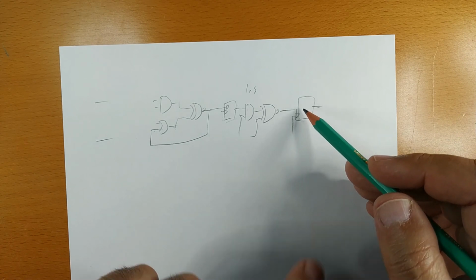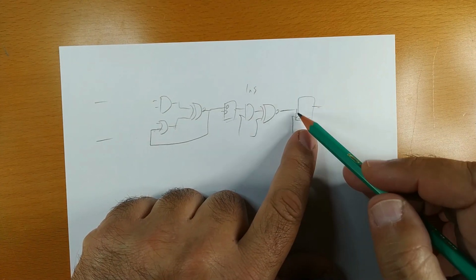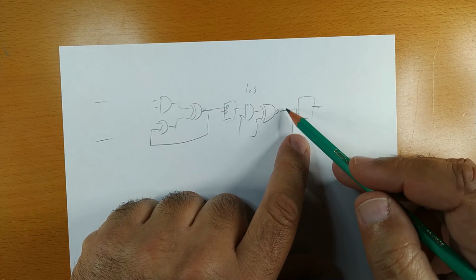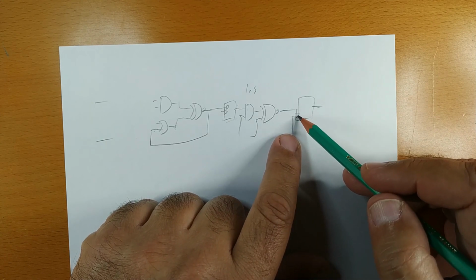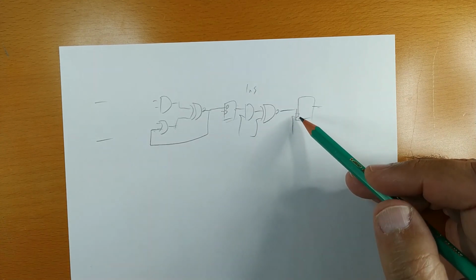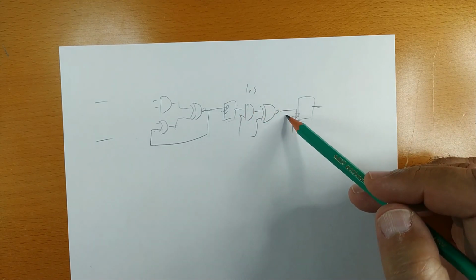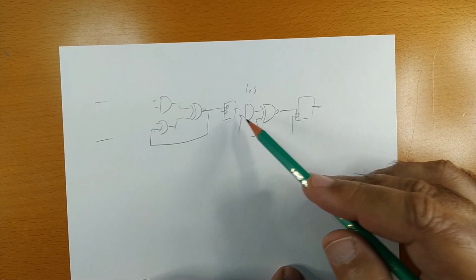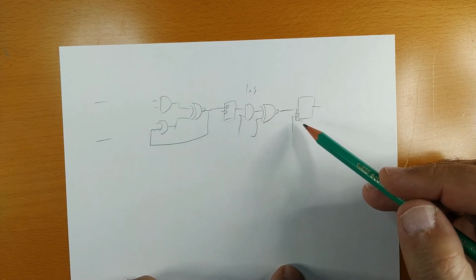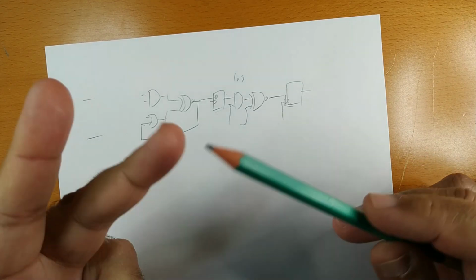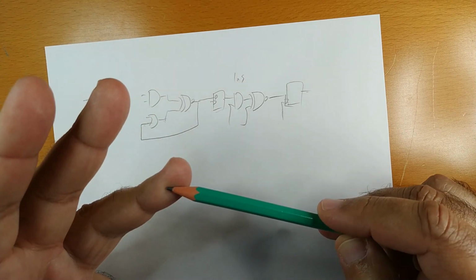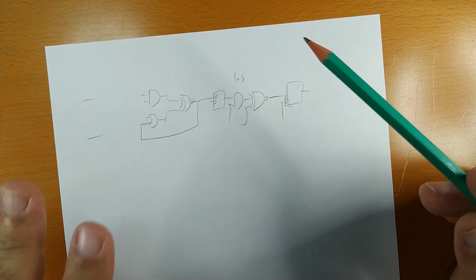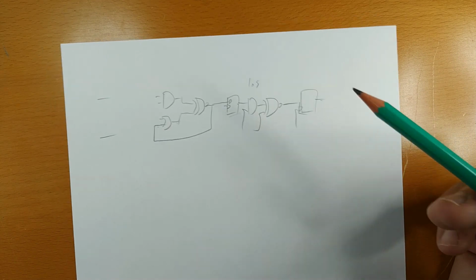Likewise, it is possible that the flip-flop will remain sensitive to changes sometime after the clock. So we might need this value to hold even after the clock has passed. And we'd call that the hold time. So setup time, hold time, and clock duration. These are the main three timing characteristics of our circuit.